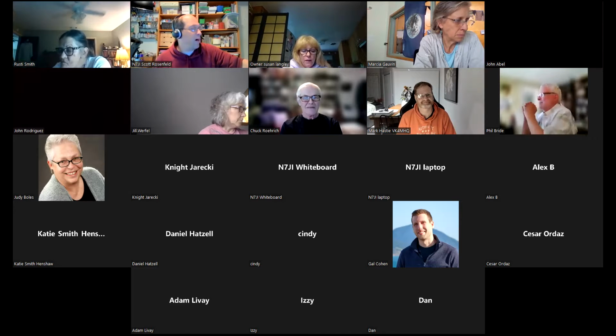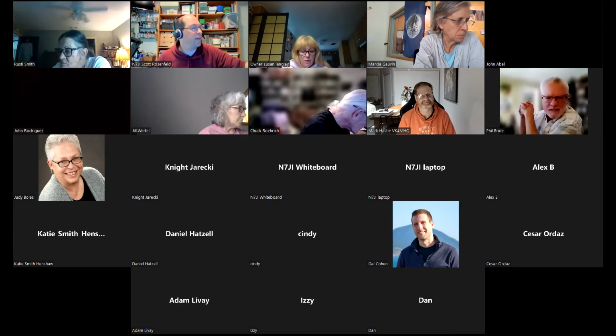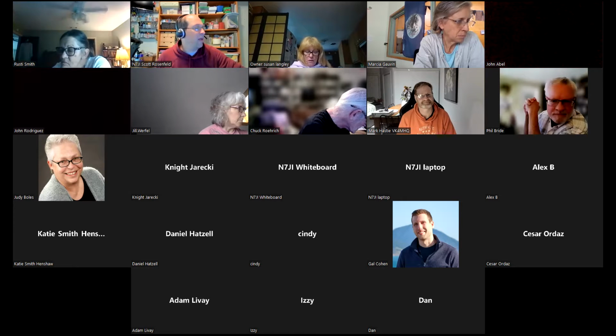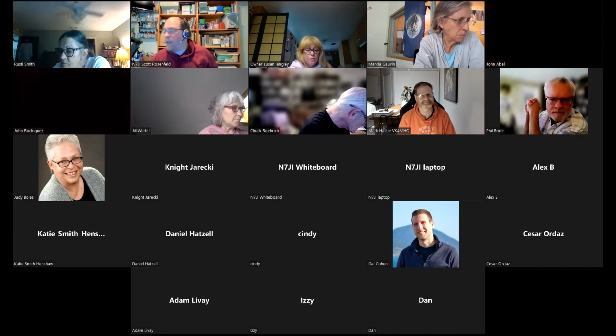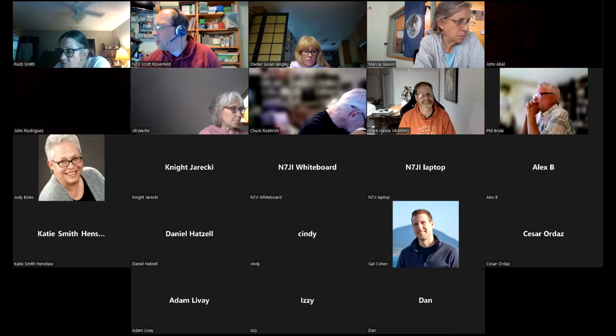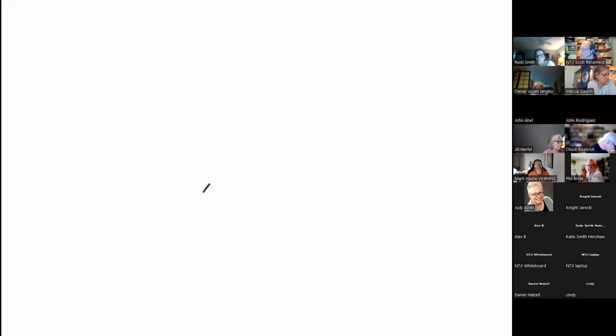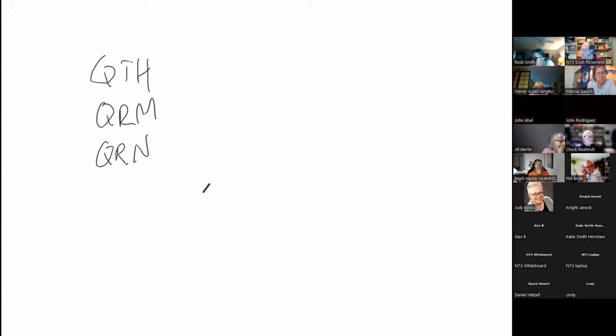Okay, what of the following is required when making on-air test transmissions? You use your call sign. You just identify the transmitter. A Q signal. There are many Q signals. The Q signals came out of Morse code. They are canned information. So a QTH is my location. QRM is man-made noise such as interference. QRN is natural noise such as lightning or static crashes. QSY means let's change frequency, or I'm going to change frequency.